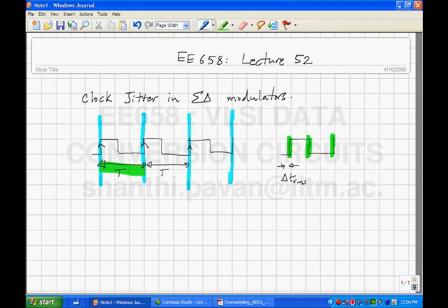Does that make sense? You can actually derive what this variance will be if you know the details of the circuit that produced the oscillator. If you know the size of the transistors and the noise sources inside them, the clock is not coming from thin air, you have to make it. The devices that go into building the oscillator have noise, which in turn results in jitter in the clock generated by the oscillator. We will not get into all those details here.